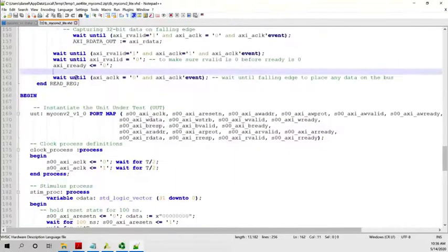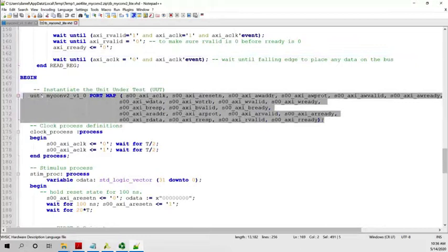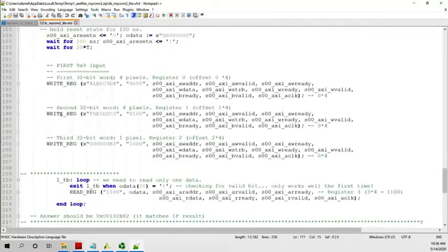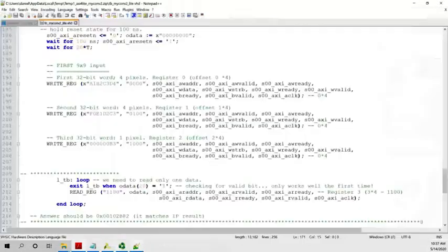So now, when you have the test bench, what do you do? Of course, you always warm up the UUT, the clock and the stimulus. Oh well, look at this. How are we supposed to test this comp? Well, you need to send actually 3 of these words, whereas in the last word only 8 bits will be used. You send 1, 2, and 3, and then after a while you retrieve 20 bits only. So let's implement that in the test bench.